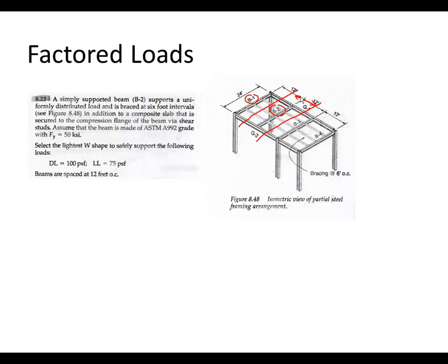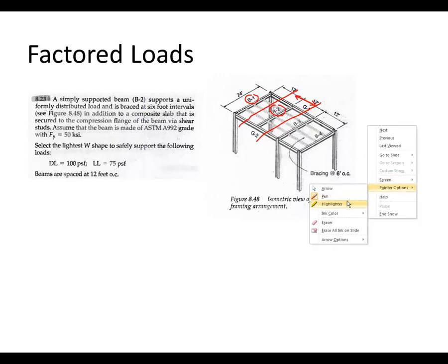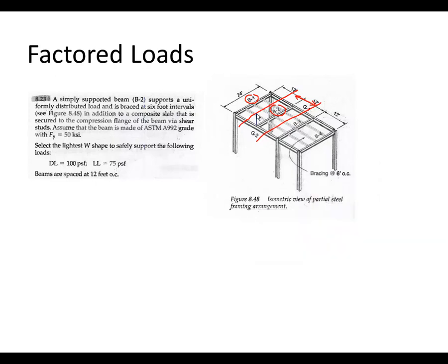And so the first thing we would have to do is take the distributed load acting in this area and convert it to an actual line load. If we were to do that, what we'd end up with is some load acting along the beam in this manner. The way we do that is back from the load tracing lesson, where we take our actual dead loads and live loads, multiply by that tributary width, and we determine the line load acting across that beam.